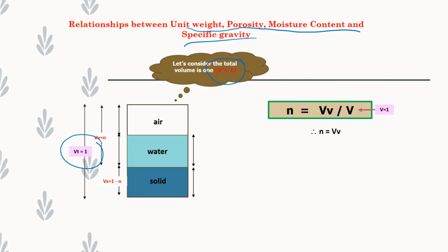So the same thing also, try to fill up all these components: weight of water, weight of solid, volume of water, and also volume of air, each of them, by using the relationship from the index parameters. So you can use whatever index parameters, for example, unit weight, porosity, moisture content, and specific gravity, to simplify that. So find the easier way first.